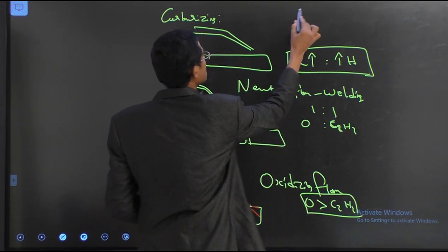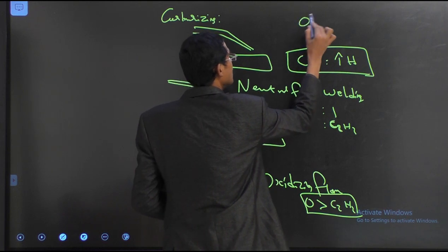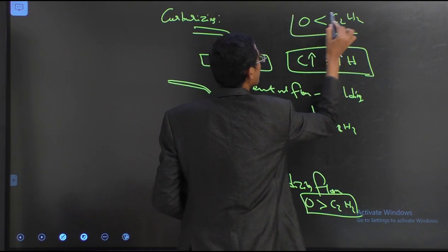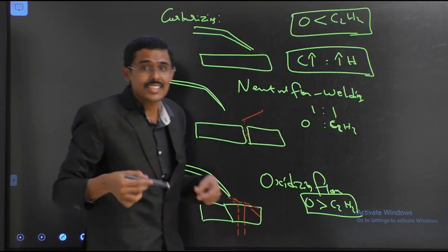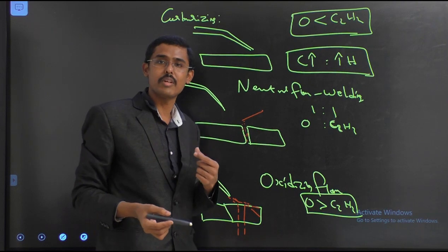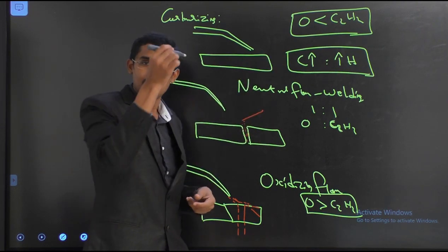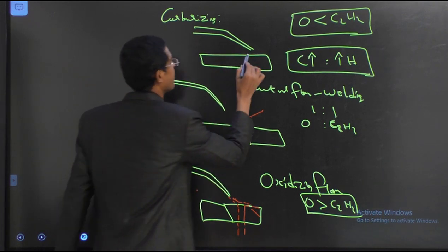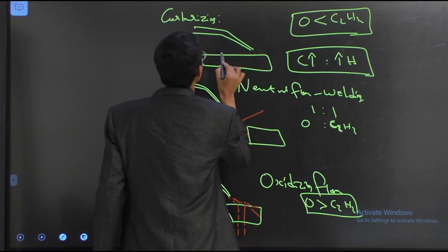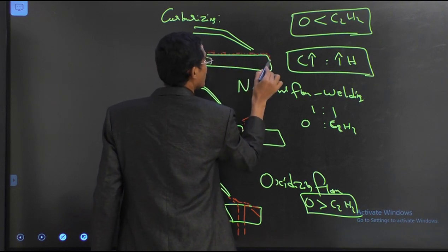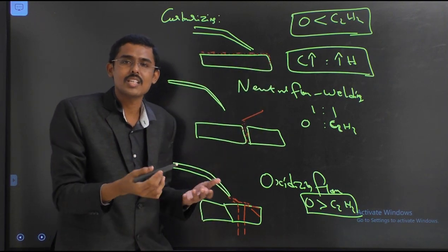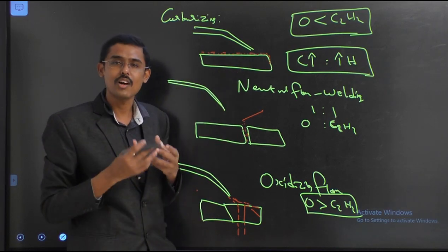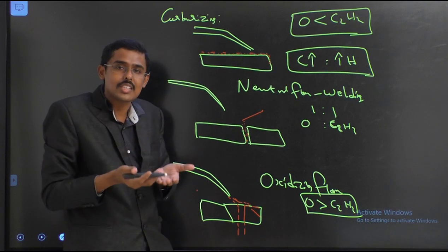Here what happens? Oxygen is less than C2H2. Here the carbon is there. Acetylene is greater than the oxygen. So what happens? The carburizing will fall on the surfaces. Carburizing treatment happened there. No cutting, no welding. It is one of the carburizing heat treatment methods, increasing the hardness.